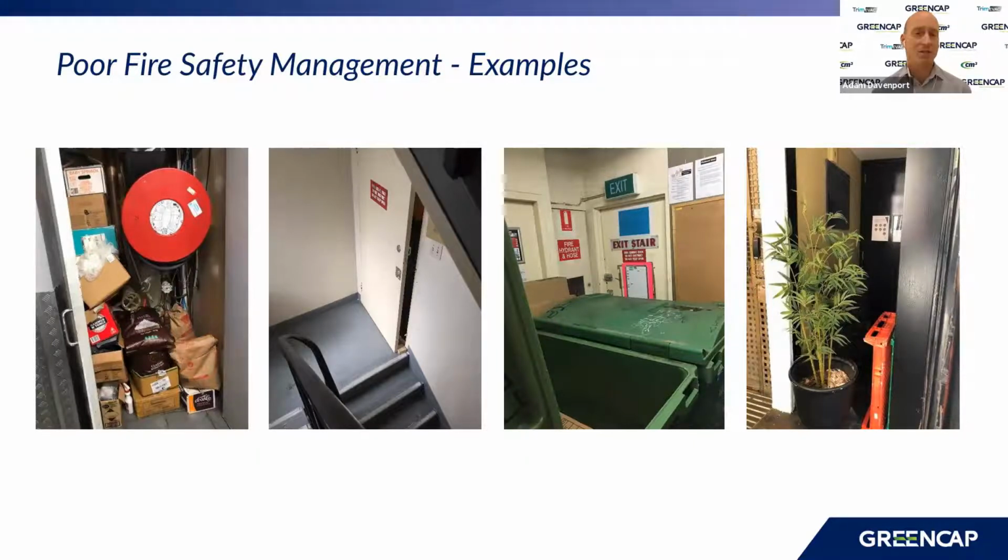When we've got occupants that may have a disability of some type that need to go into a refuge area and get away from that fire, we use those fire stairs and we keep them on that platform until firefighters can carry them downstairs in a safe manner. Same with obviously everyone evacuating the building. So don't chock open the doors, because if you chock open the doors and an emergency occurs, that smoke can potentially go into that environment, and you've got carbon monoxide risk going into that environment where it should be a safe haven.